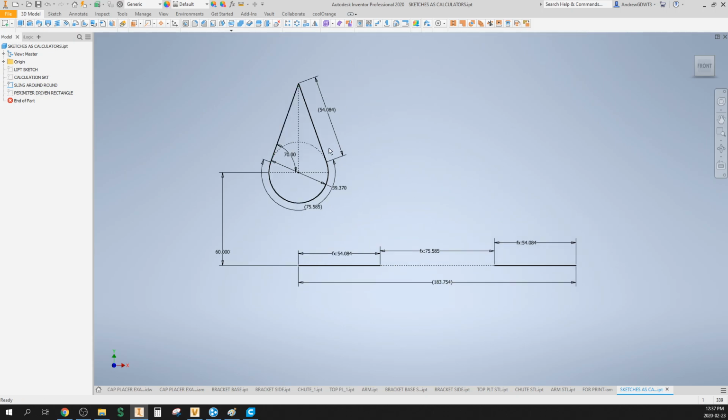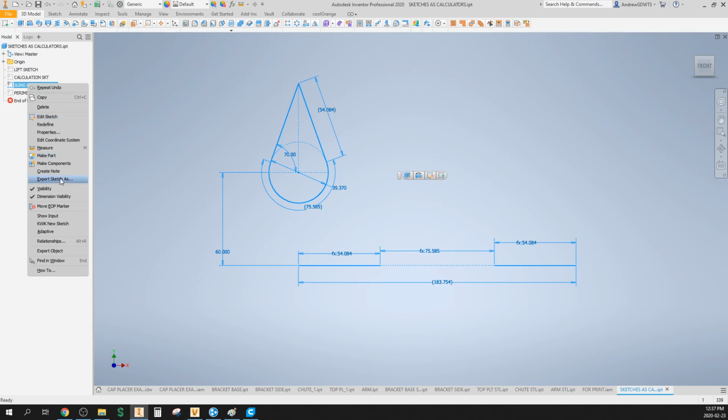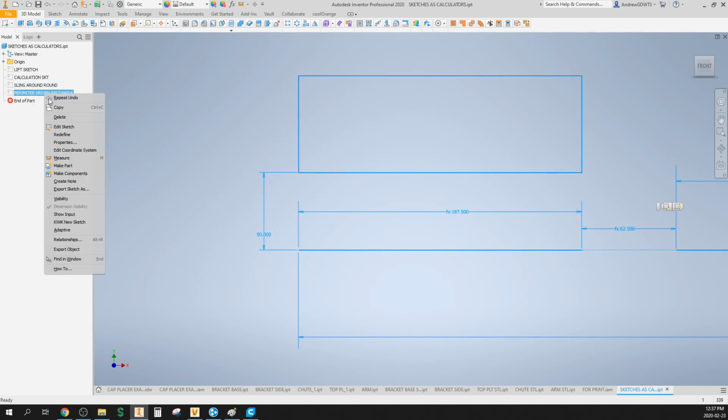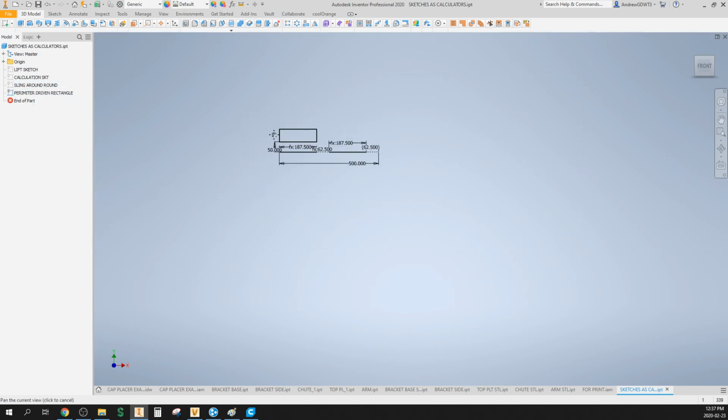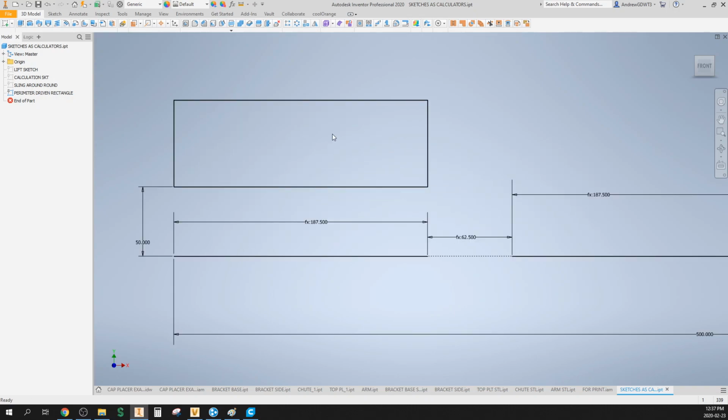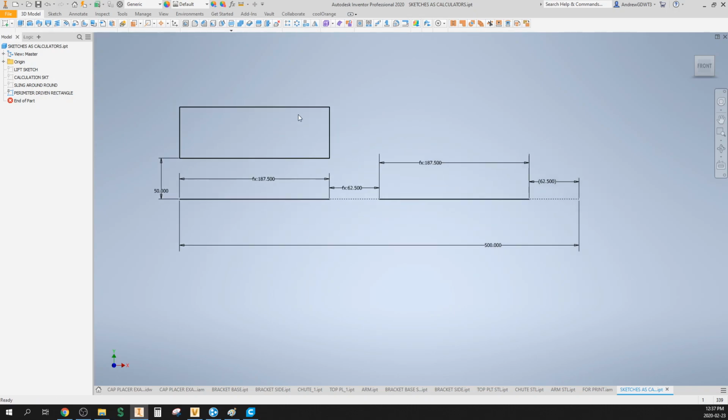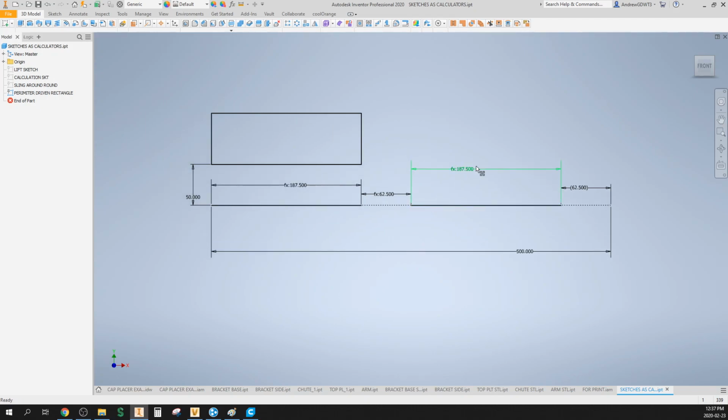That one's pretty slick. I like using this one. The last one is kind of neat. This rectangle has two inputs. The perimeter is the main driving one. In this case, it's 500. And the other one is the aspect ratio. So I've set up these lines to be equal to these lines and the short lines to short lines here.